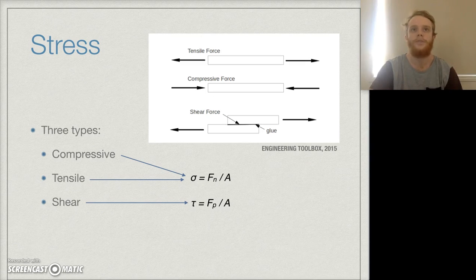The third main type of stress is shear stress, which is where the force is applied perpendicular to the face of the object. To explain this, imagine the glue in the image is replaced by a bolt through the two objects. To separate them, the bolt would be broken in half at the point where the two objects meet, or more correctly, sheared in half.